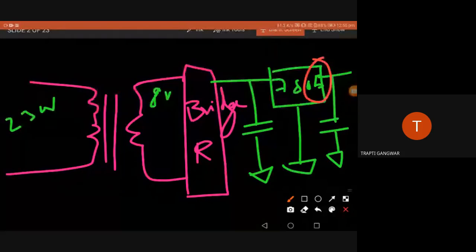My point is, when you see a circuit, you should start thinking about how this is working, what's the problem happening, why I'm not able to understand. Mostly you don't understand because you're not able to understand what this part is doing. So first thing, what are the requirements here? I need to generate a 12 volt or 9 volt or 5 volt, and I need to generate a high motor voltage, control the relay here, this much voltage. And I need to sense the signal. What signal? The tank is high, I'm getting a high at this part of the circuit, and etc etc.